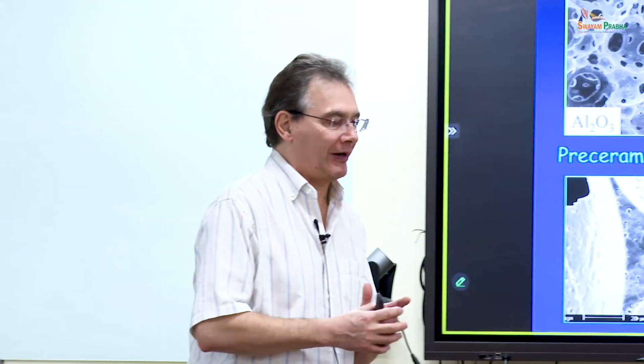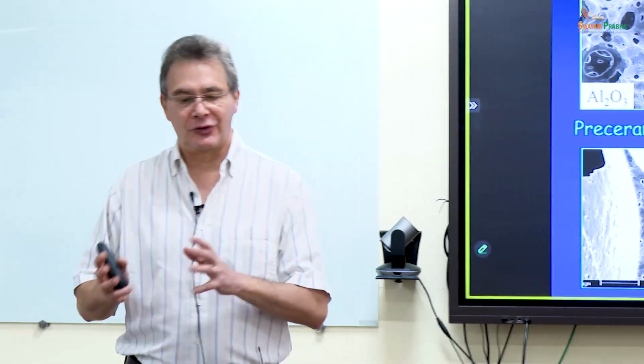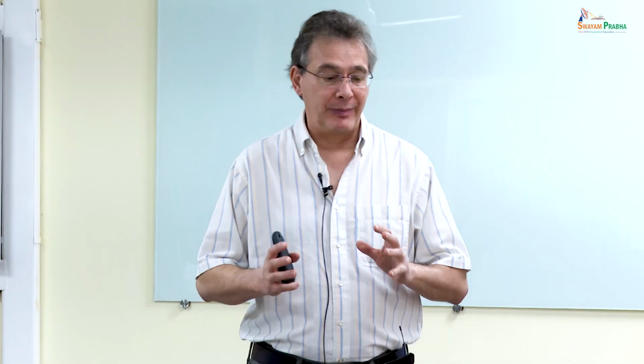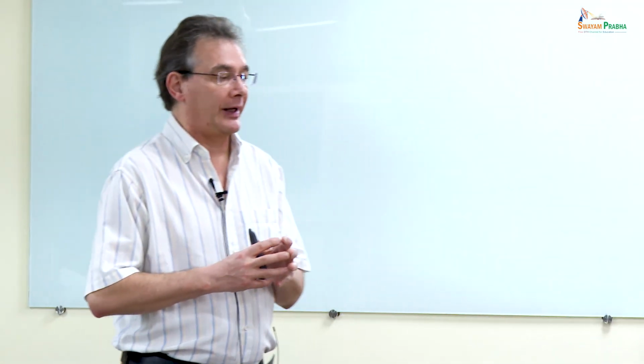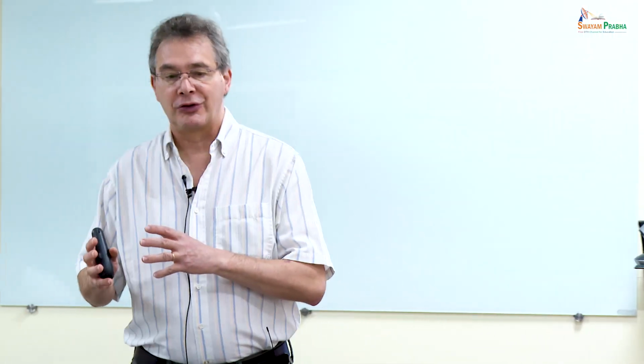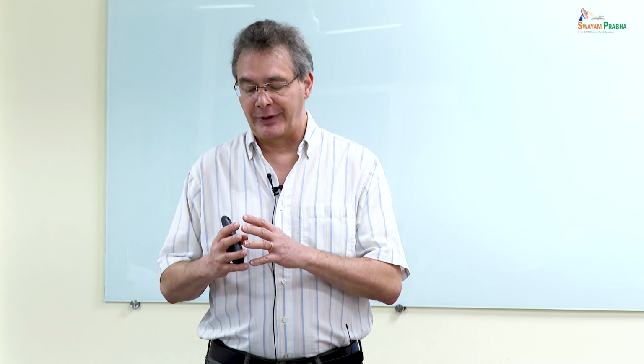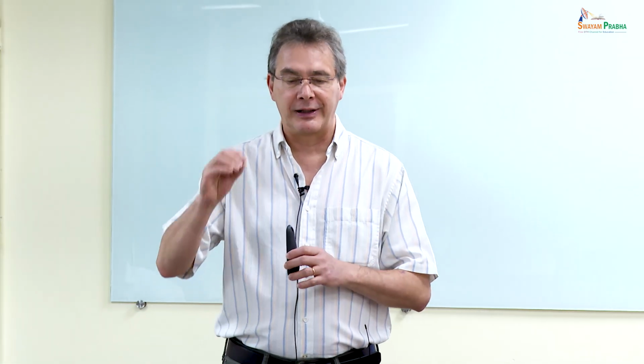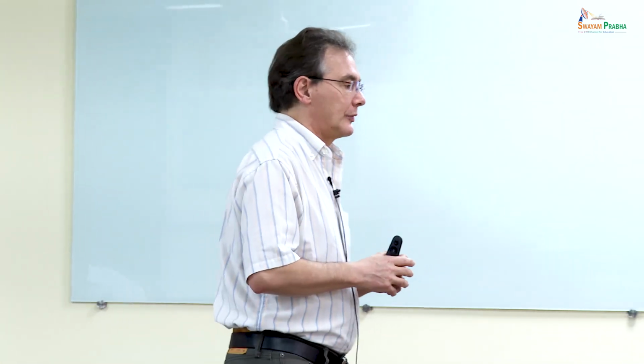So let me explain again the rationale for discussing porous ceramics in general and how that ties to the topic of the course on additive manufacturing of ceramics. As I mentioned, most of the applications for components that have been manufactured by using additive manufacturing contain porosity. And the advantage, of course, of additive manufacturing is that you can control precisely the position of the pores, the size of the pores, the shape of the pores, the amount of the pores.